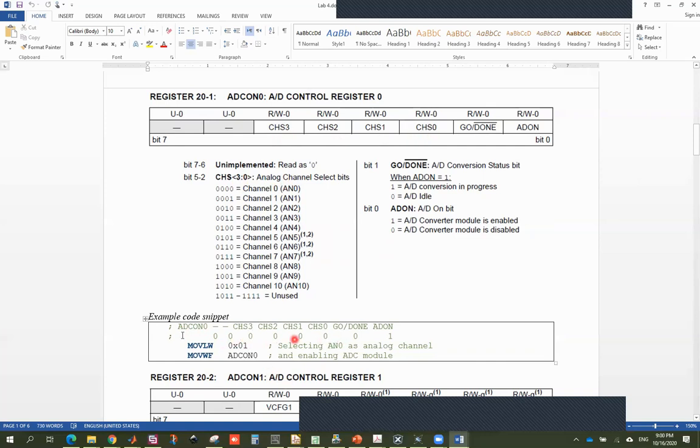Whenever you write assembly code and you come across a new register or new SFR, you can copy the name of the register along with the bits of this register as a comment inside your program code, and in the next line you can write the data bits under these bit names, so that when you look at this, you can easily understand why you are copying this data in this register.